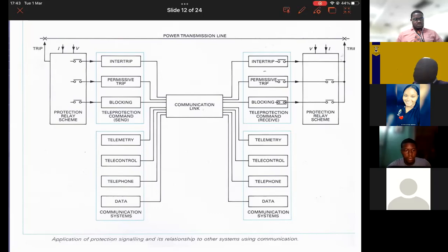You would have to walk along the transmission line to identify where the fault has occurred. Today, in the substation, you can interrogate that distance relay, and it tells you within a couple meters where on the line the fault exists. And that is all a part of the whole communication system.